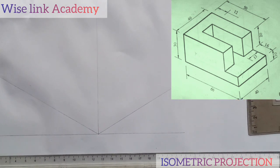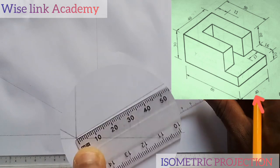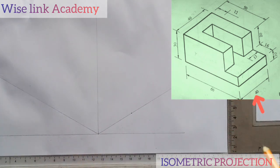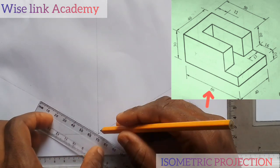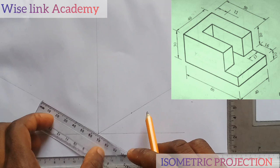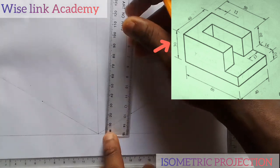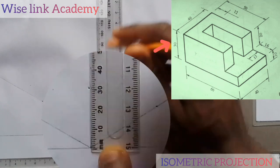So after producing my isometric axis, what's my next task? My next task is to get my length, breadth, and height. For my breadth, from this point to this point is 40. As you can see, my arrow is indicating. For my length, from this point to this point is 66. 66 from here down here is 66, right? All right, the entire height there is 30. So from this point to this point, I'll measure out 30.